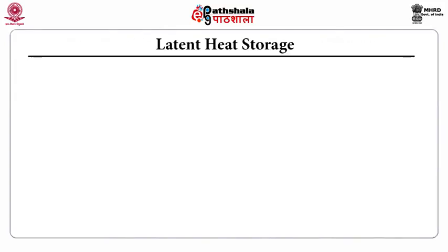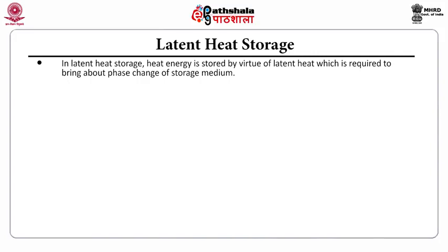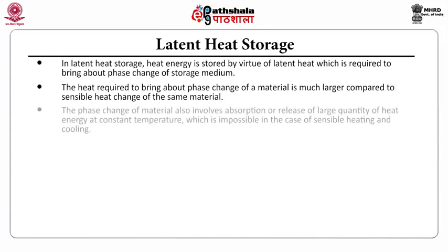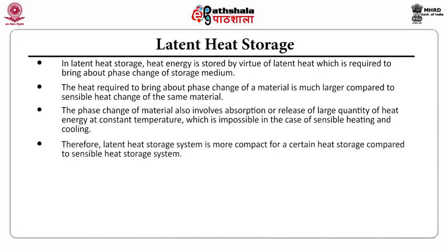Latent heat storage. In this storage, heat energy is stored by virtue of latent heat, which is required to bring about phase change of the storage medium. The heat required to bring about phase change of a material is much larger compared to the sensible heat change of the same material. The phase change of a material also involves absorption or release of a large quantity of heat energy at a constant temperature, which is impossible in the case of sensible heating. Therefore, latent heat storage system is more compact for a certain heat storage compared to sensible heat storage.